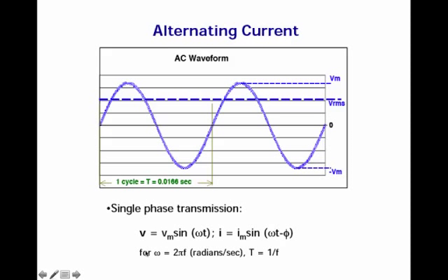It changes direction 60 times a second, right? Or we say 60 hertz. So you've probably heard the term 120 volts, 60 hertz. And it sounds about like that. That's about 60 hertz. And that's the sound you hear from devices like transformers that draw a lot of current, because that oscillating current causes changing magnetic fields, which put forces on the wire and make them wiggle at about 60 hertz. So that is the sound you hear.